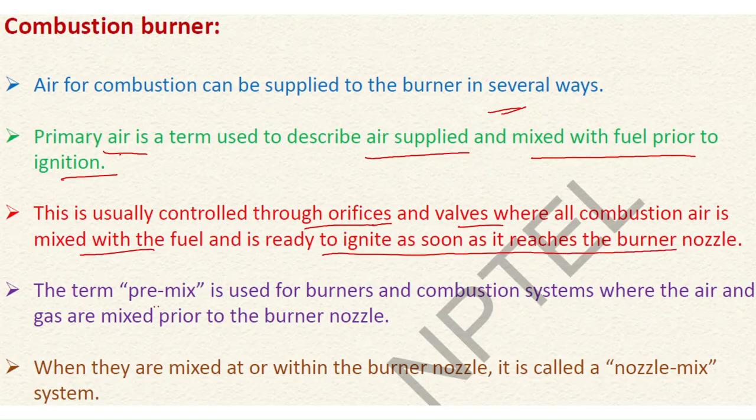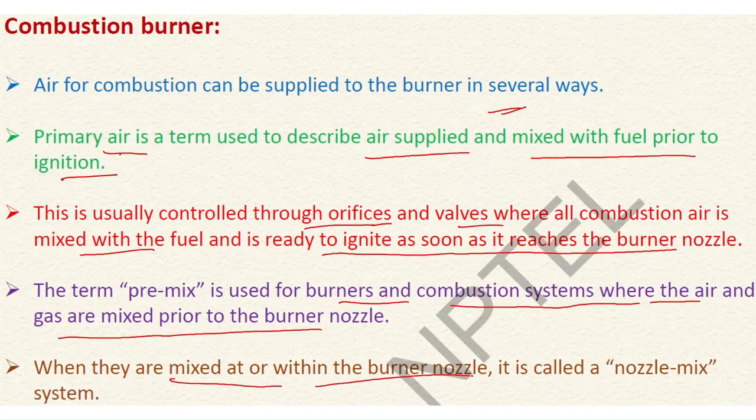The term premix is used for burners and combustion systems where the air and gases are mixed prior to the burner combustion. Similar to the one in flame, here also premix and non-mix is there. So sometimes the air and gas or fuel is mixed prior to injecting it into the burner, and sometimes it is mixed at the mouth of the nozzle itself. When they are mixed at or within the burner nozzle, it is called a nozzle mix system.